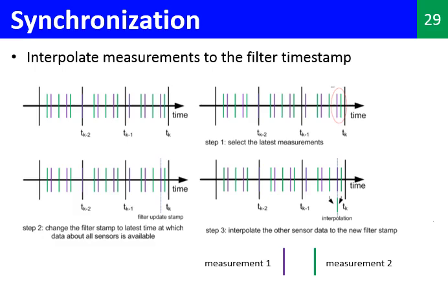In this figure, we can have camera measurements in purple color, for instance, and IMU readings in green color. The reason why the frequency of the Kalman filter is low is because we want to give it more time to do all the matrix calculations regarding prediction and update steps.